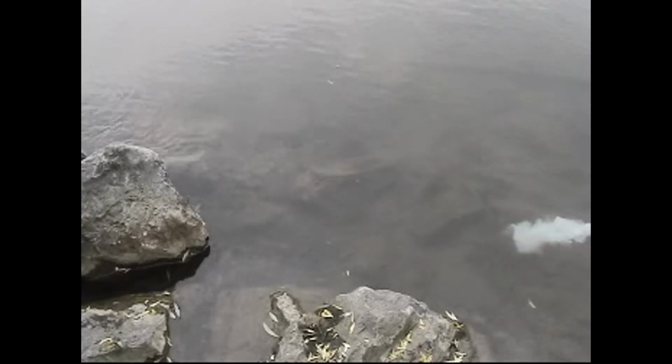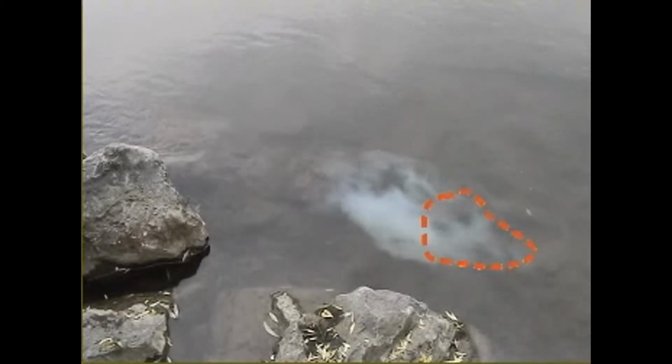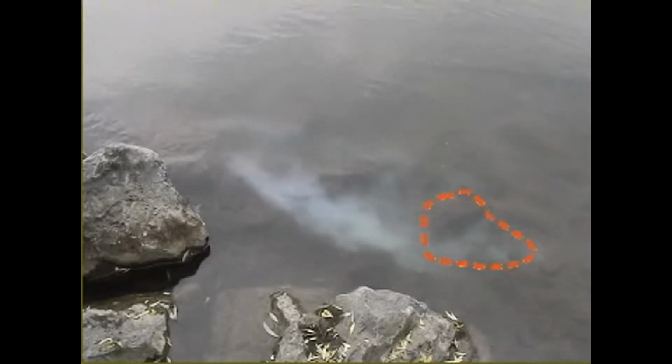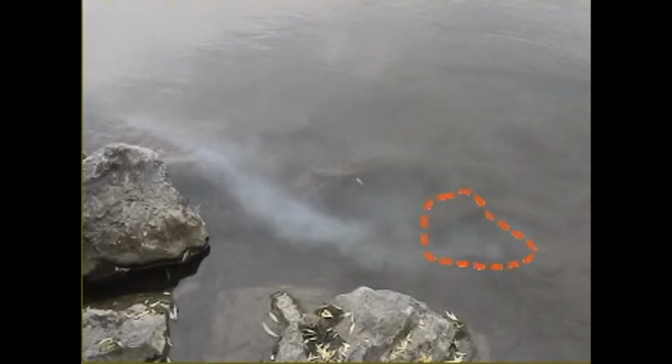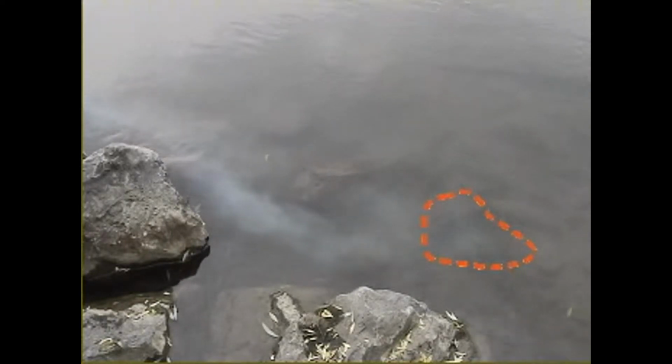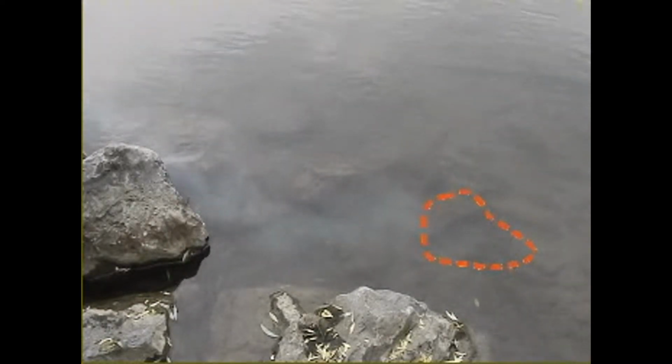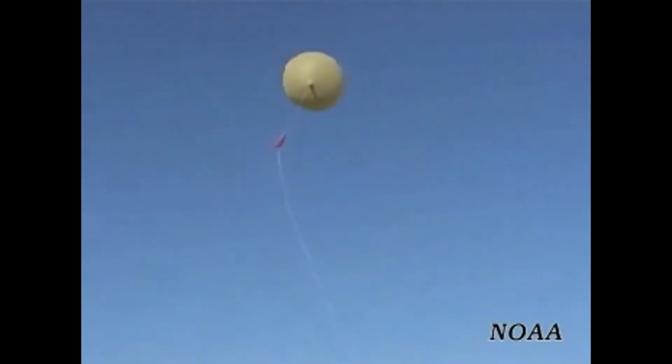In a few cases, it's more useful to follow a specific fluid mass through a flow field using a Lagrangian reference frame attached to the mass. Here, the blob of white water is followed as it moves downstream. But if we mark the instantaneous boundary of the blob of fixed mass at a certain time, then we can watch the water flow through this boundary while the original white blob flows on. This is the Eulerian approach. The Lagrangian approach works best, for example, in meteorology, where a weather balloon drifts along with the prevailing wind.